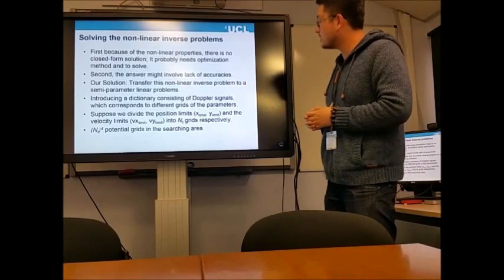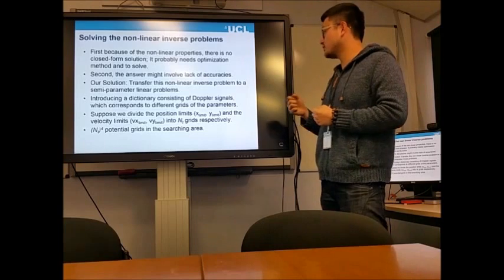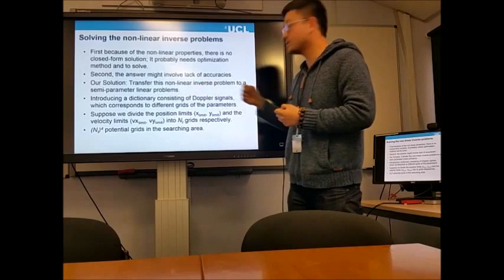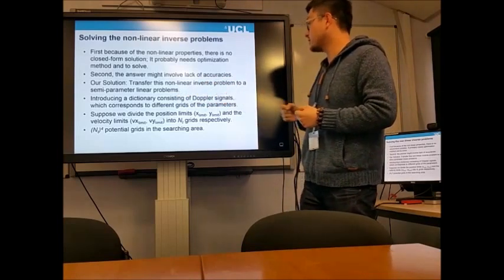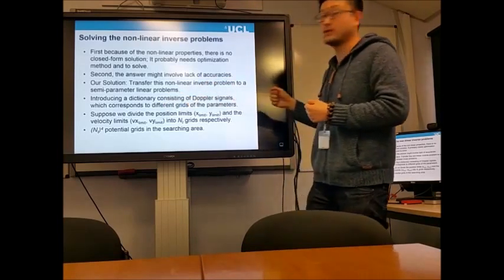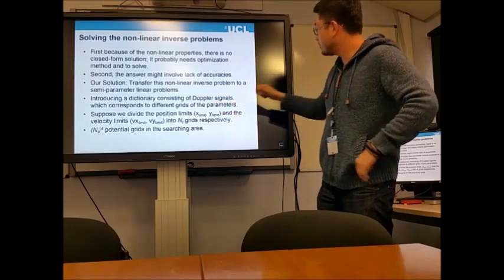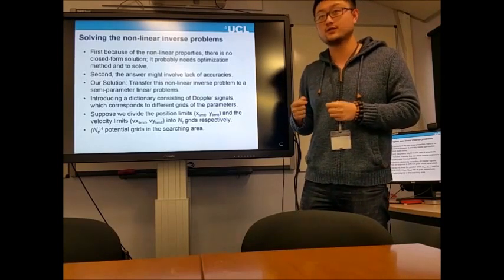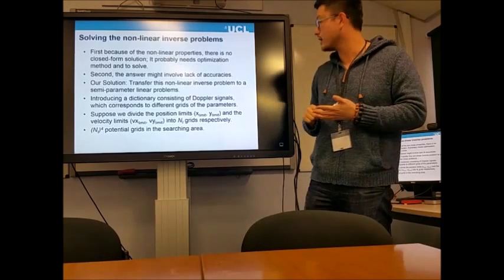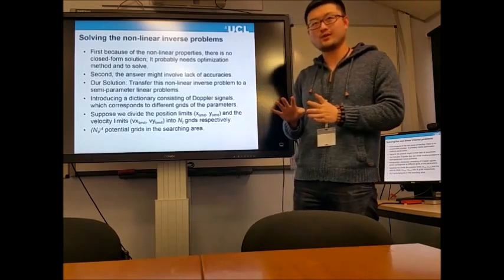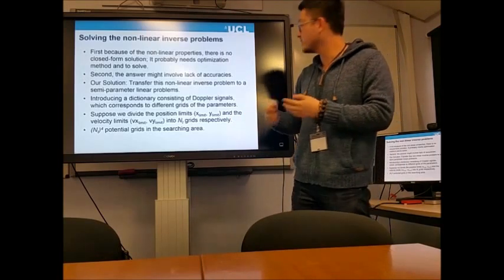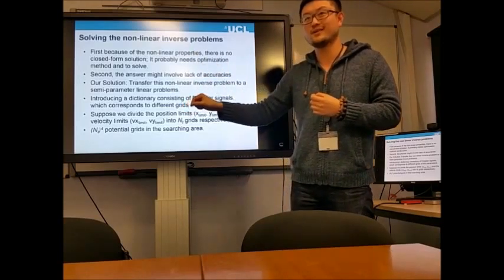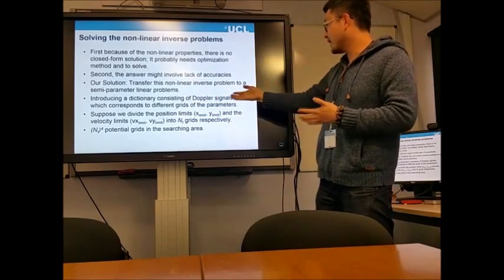Our solution is to transform this nonlinear inverse problem into a semi-parametric linear problem, by introducing a dictionary of Doppler signals corresponding to different grids of the parameters. Here, the parameters are the 4 variables in the state of the target: x, y, vx, and vy. We separate these 4 variables into grids, and we make a dictionary of the Doppler signals that can be echoed from each particular grid. And then, if we have that dictionary...